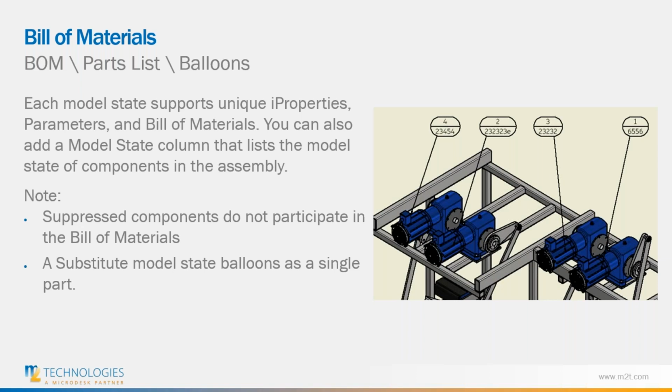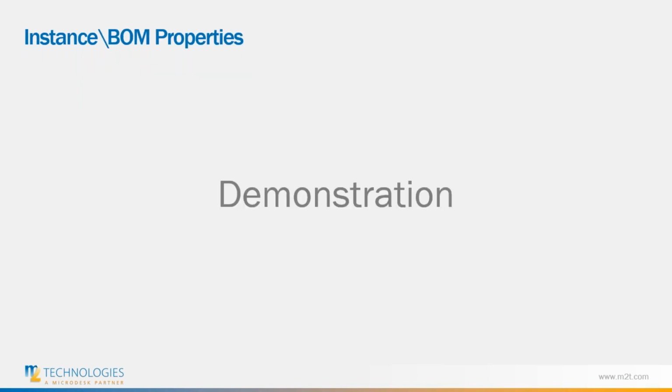You want that to show up, you may have to go into the styles, the parts list, the parts list goes on the drawing, and in there you might have to add that custom property value. And the same thing with the balloons. You might have to create a custom style there. In our example, maybe a split balloon that's going to show not only the item number, but also that custom instance property in the balloon. So let's go over that.